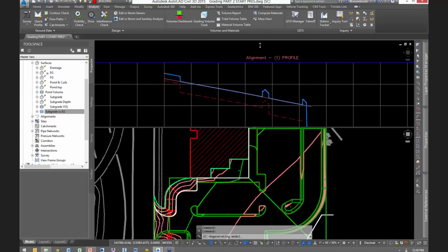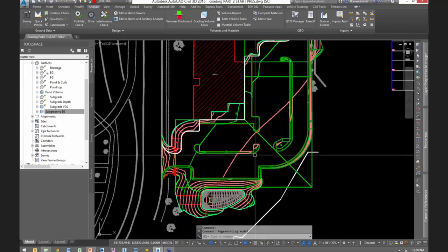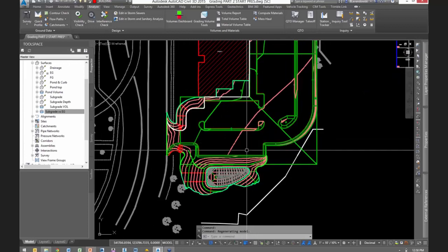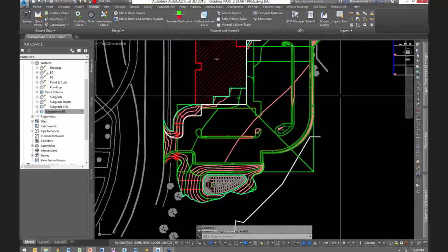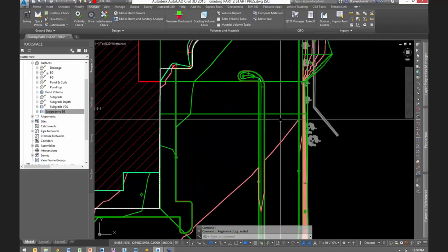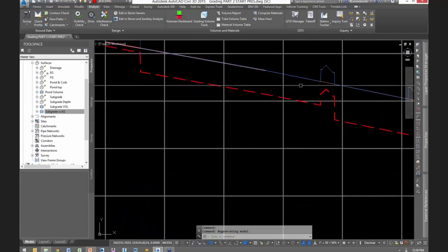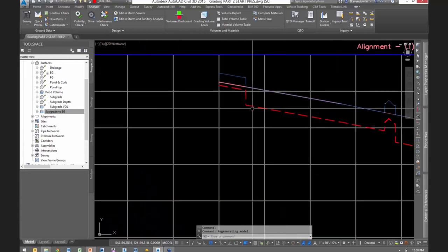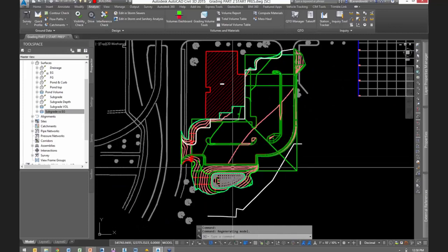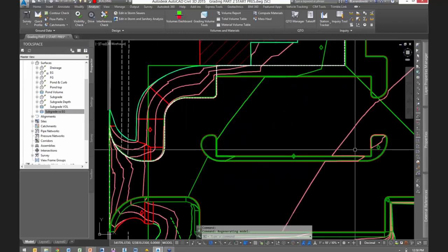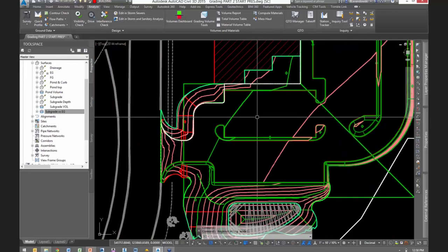So that's the gist of what I wanted to show today, and it's all about pulling quantities out of there. So we use QTO Manager. We use basic volume surfaces for a pond capacity. And I'm going to use a series of surfaces, volume surfaces and tin surfaces, to generate a dynamically linked subgrade surface over here. And how much you want to quantify what you need for your subgrade surface, that's all based on those polylines. And those polylines are basically just offsets from what I created for my curb lines there. Just a little bit of plain AutoCAD work there.